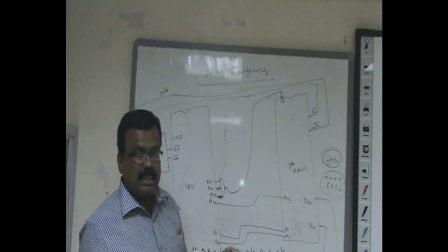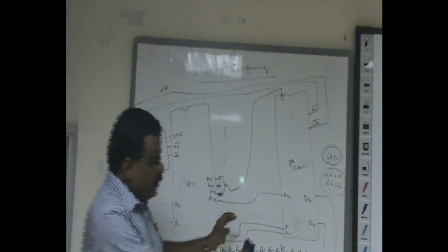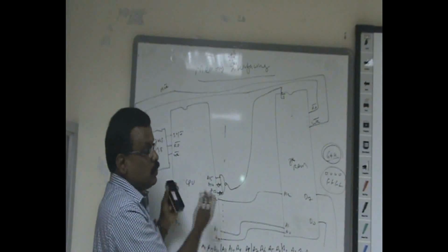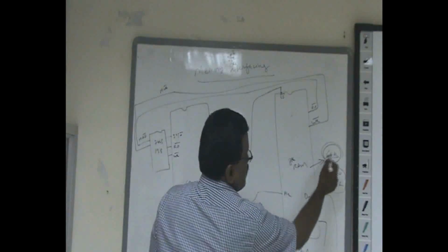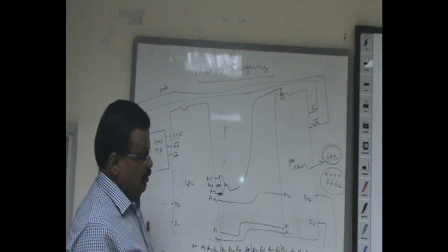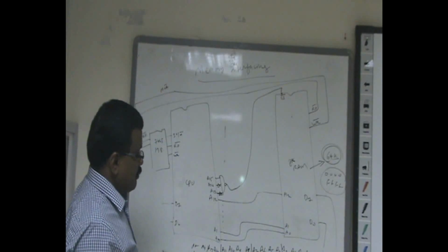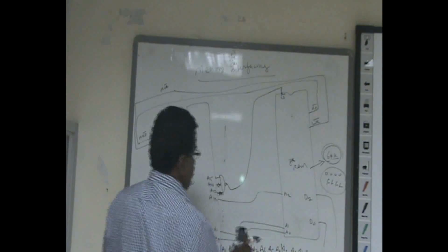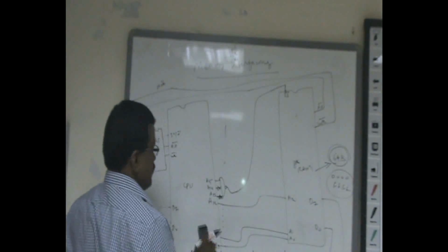So from this what you can understand is, these kind of 8 8K RAMs can be interfaced with this CPU. So 8 into 8K, total memory is 64K. Okay. This is how they design the interfacing logic between memory and CPU.